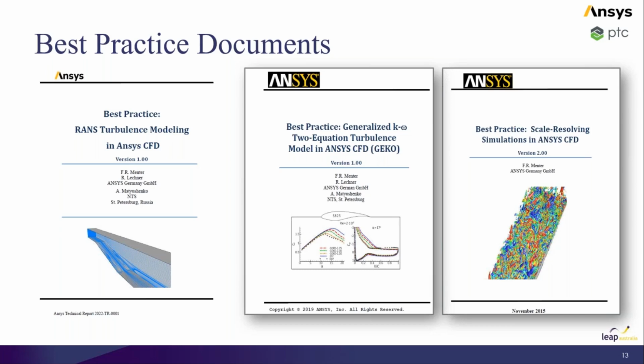I'd encourage you to read some of these papers because they will show you all the checks you need to do. And it is so important that when you're using these models, you follow some good practices of checking mesh independence. You could see how things like mesh adaptation in the work that was just presented was so important.